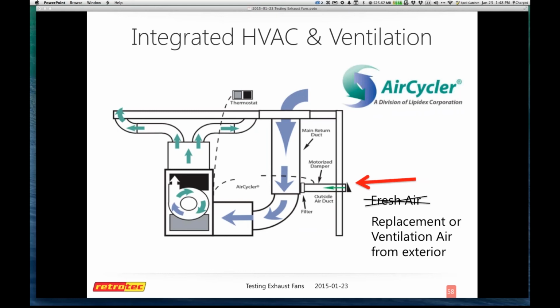Some municipalities accept only exhaust. Some say you must have a balance of exhaust and a supply system. So that conclusion can depend on what program you're following. So there's a gray area there as to what you're required. The issue is how can I test this or determine the amount of flow that is happening or coming into the system. This is a requirement to be measured in California. So they want to know how much of this air.